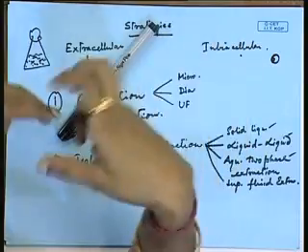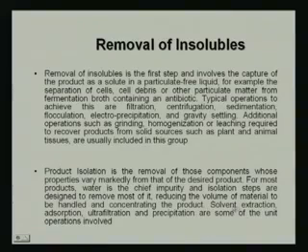Suppose our targeted product is a little bit hydrophobic in nature. That means water is not a very good environment for this targeted product. So, we can easily go for the solvent extraction method. Solvent extraction is one such example, but you have to have a prior idea of what your targeted product is and how we can proceed to isolate it from the bulk chemicals.